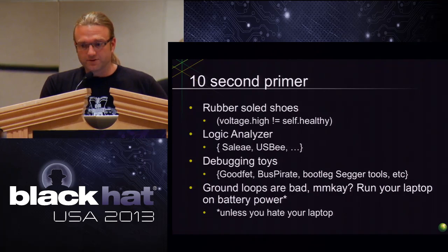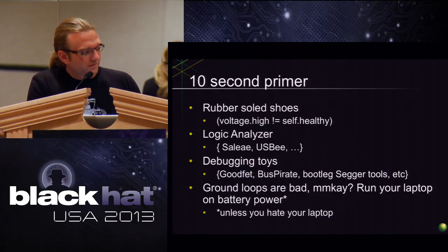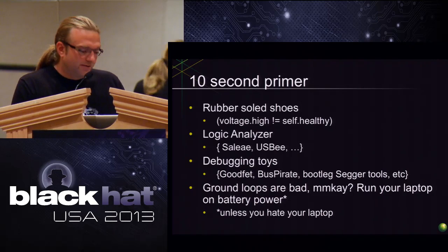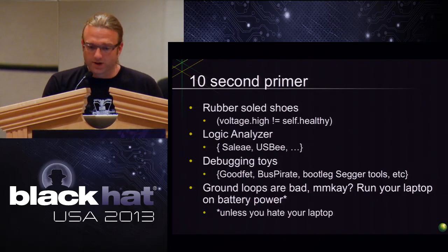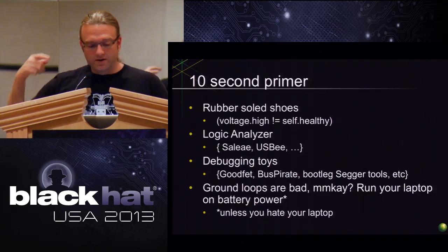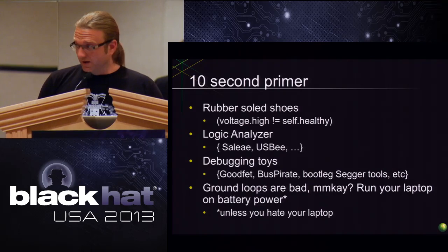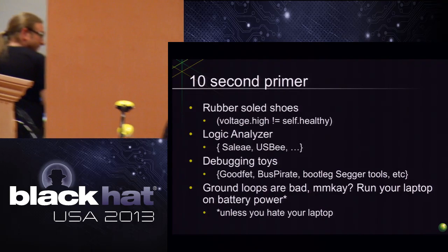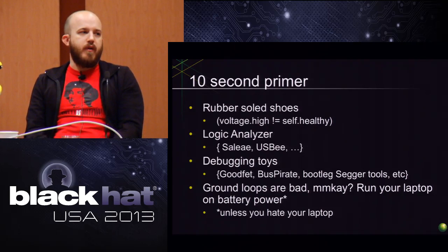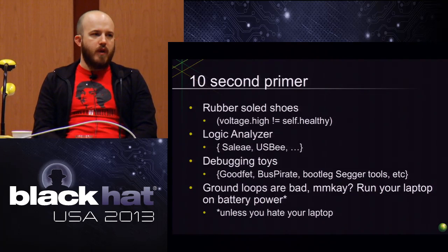Almost every type of Harvard chip or any sort of embedded chip that you're going to look at will typically have a custom debugging board. You can also start playing with the Goodfet, which we've done quite a bit for this project, but sadly we're not releasing anything yet, because it never quite worked the way we wanted. Bus Pirate, I mean, typically you want to be able to figure out what's going on the wire, then you want to figure out how to actually debug and start playing with things. Right, it's all just about figuring out what are those interfaces there, right? So just figuring out what talks to what, how can I interface with that, how can I monitor how the pieces are interfacing with each other, and then in what ways can I influence execution state.